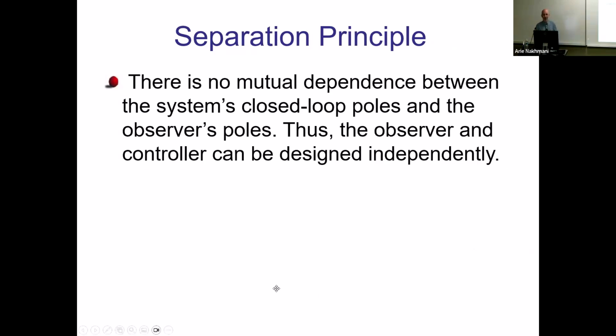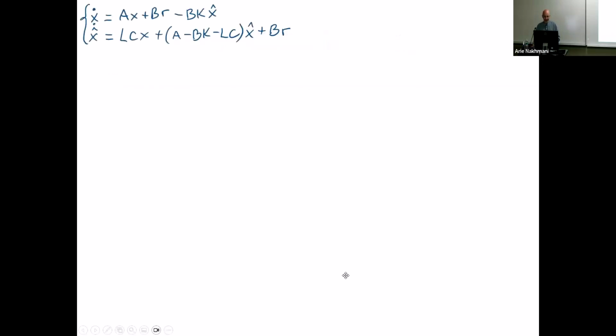But you can. And this is what the separation principle is saying, that you actually can. You can find a realization of that system in state space. This is a little bit tricky. You need to find a particular similarity transform for that, that will completely separate observer and controller, and they will be decoupled completely in that realization. As you remember, a similarity transform is not changing the transfer function or any other properties of the system. It's still the same system, a different realization of the same ordinary differential equation, practically speaking. You have many of them, so you can choose. We will choose one specific one, which is a very interesting one.